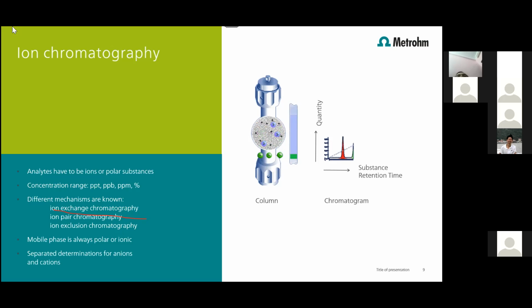It is specific to every ion, and you can see the peak. The software calculates the area of this peak to measure the amount of ion in the sample. The retention time is the evidence to identify which ion differs from the other ions.